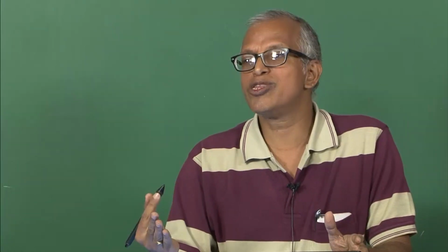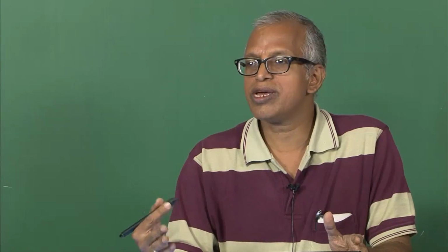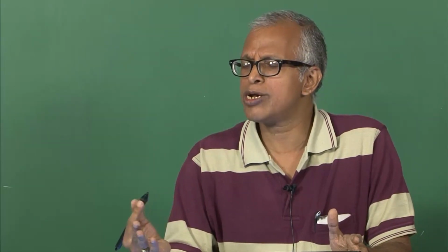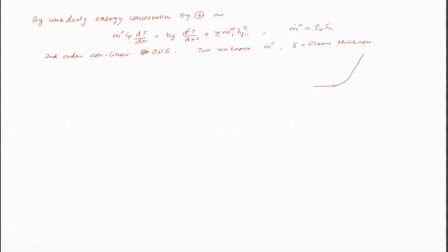Whereas in the reaction zone we will also have to use some approximations, that is the convection will not be very predominant. If you look at, I take this as the ignition temperature, T ignition, and this is my x, this is x equal to minus infinity, this is x equal to plus infinity, and this point is T ignition, and this is your Tf, this is your Tu.